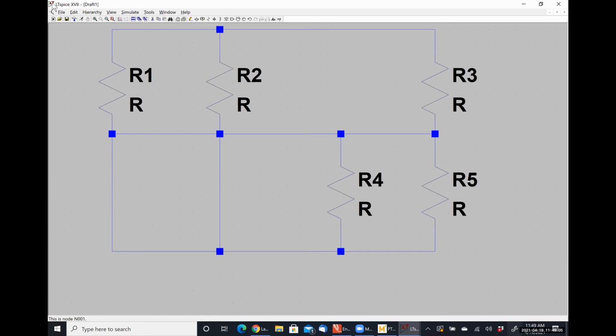Another thing that I want to point out is that LTSpice does everything as a sine function. So if you want to put in your answer, express it as a sine as well. If you put in a sine, you get out a sine, and everything else should match. The other way would be you would have to put in, let's just throw in a voltage source real quick here.